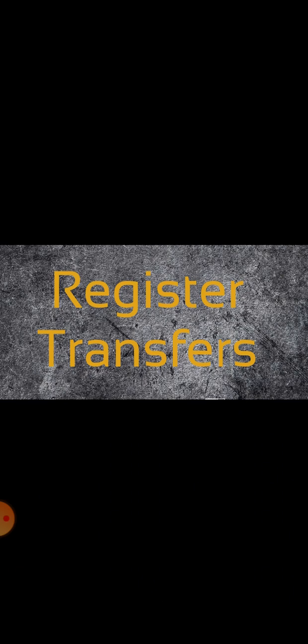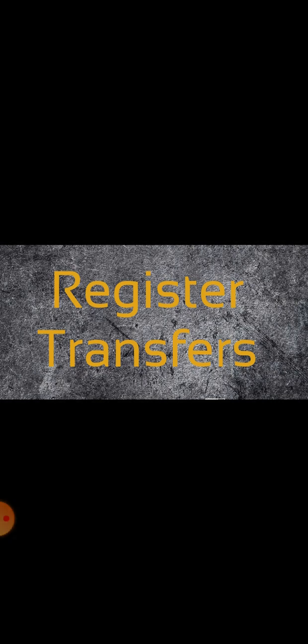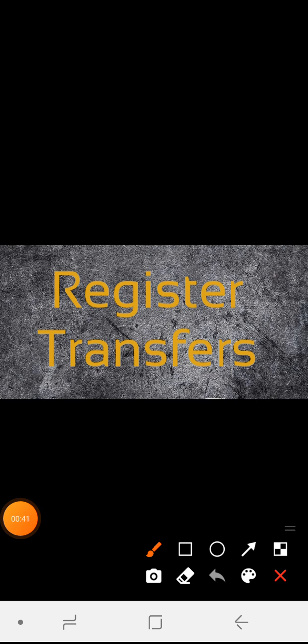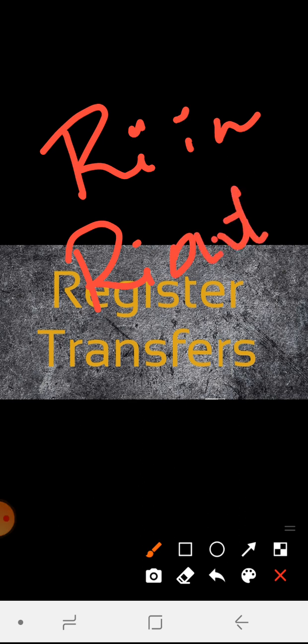So we know that whenever a program is getting executed, a number of steps are involved where data has to be transferred from one register to another register. The register acts as a temporary storage where it has to store the data from the bus, or send the data on the bus. Whenever we use a register to hold the data or to send the data on the bus, it uses two control signals: Ri in and Ri out.